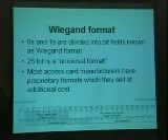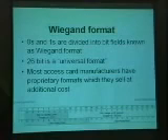Manufacturers of cards will quite often say, right, I'll tell you what, we've got this super secure version, which is actually 36 bits, and we don't sell the site codes to everyone. We'll give you your own site code, and we won't sell it to anyone else. So just remember, when you're buying your 26-bit card, quite often there's a chance your next door neighbor might have the same facility code, and therefore might have duplicate cards.